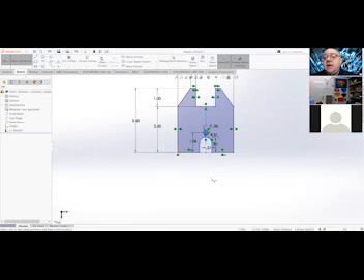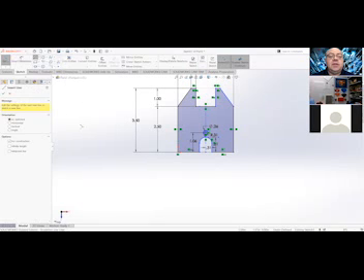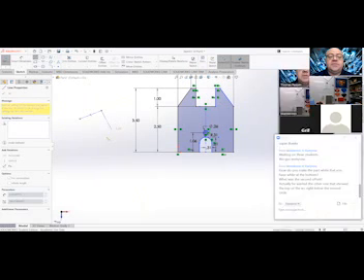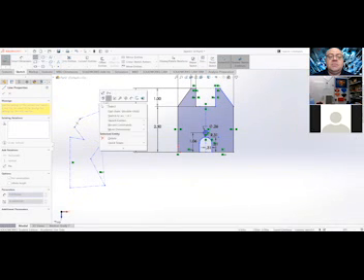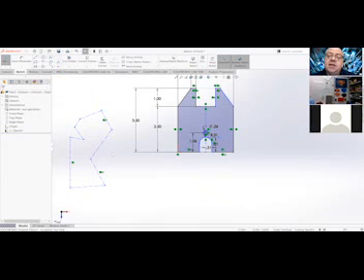And we don't have to worry about deleting them because they're not going to ever print, and they cannot become a 3D object. So if I was to draw in centerline mode and just draw some off the side and a big old messy thing, I never have to delete that because it can never, ever, ever become a 3D model. It's just there and it won't affect anything. Okay, so center lines are really good that way.